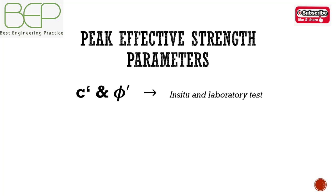A number of different laboratory and in situ tests are available for determining the peak strength of soils. Except in the case of very small structures, the strength properties of cohesive soils are normally obtained by testing good quality undisturbed samples in the laboratory. The stability of earth-retaining structures will normally be at its minimum in the long term, so that for most designs the peak effective parameters are required for earth pressure calculations. These can be obtained as follows.